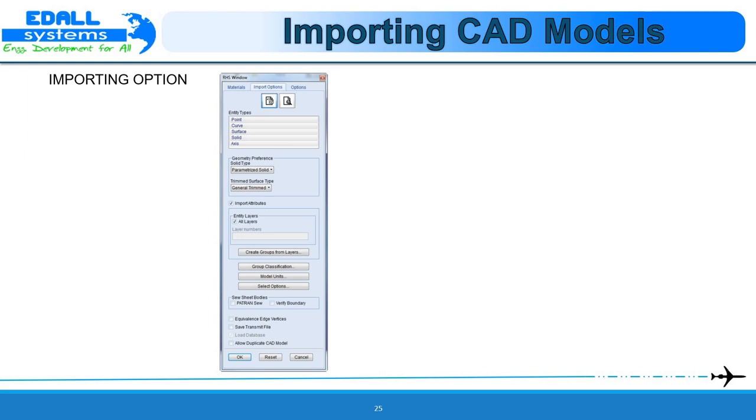Where an option exists, the older CAD import can be activated by switching off the import to Parasolid checkbox on the import form. In general, the CAD model contains more data than you need for a CAE simulation model. A number of options for filtering or limiting the import are provided. When you specify a CAD package on the import form, one or more subordinate forms appear so that you may define the filtering options. You can filter based on entity type, surface type, and CAD layer. Plan ahead in your CAD modeling and use layers or colors to separate out entities that you want to exclude from the analysis model.